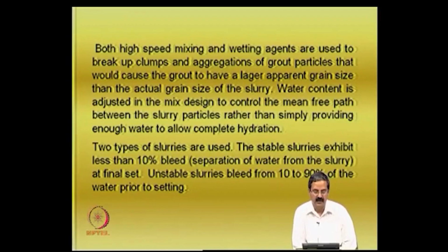Okay. Another important thing is that the water content should be sufficient so that water is available everywhere in the grout, rather than simply having enough water for hydration. The objective here is to see that the water is well distributed in the complete grout.